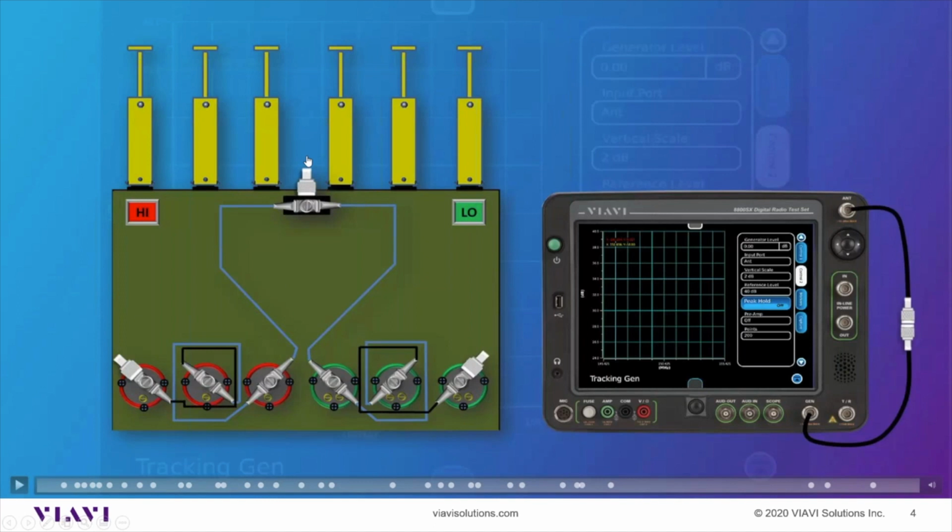So you only want basically less than a dB of loss through your cavities here, so you've got pretty close to 100 watts coming out. At the same time, simultaneously, you're going to have a receiver frequency coming in at about 80 or maybe all the way down to -100 or maybe a little bit lower.